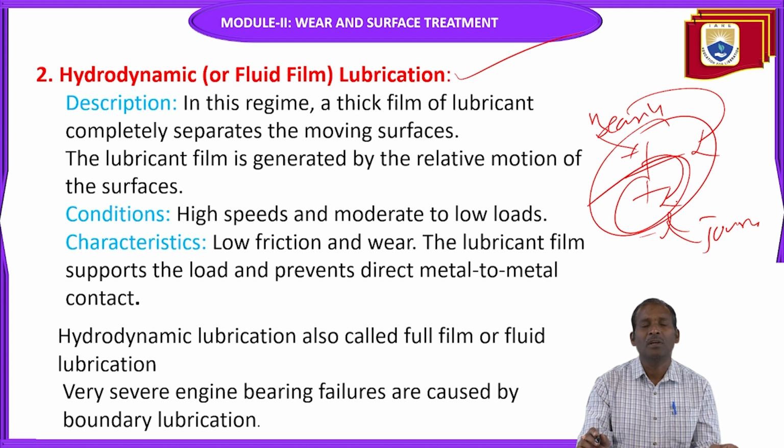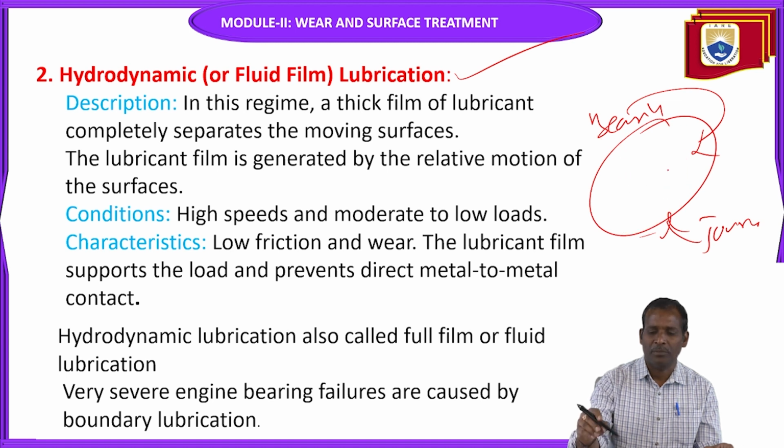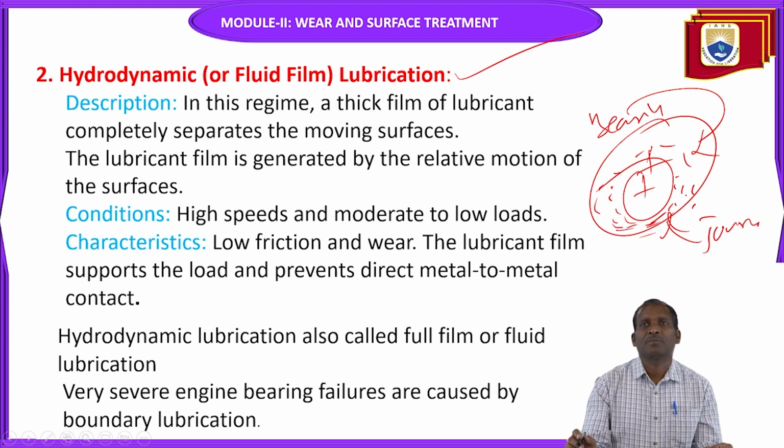In hydrodynamic lubrication, the thick film of lubricant completely separates the moving parts, the journal and bearing, with the maximum film thickness.